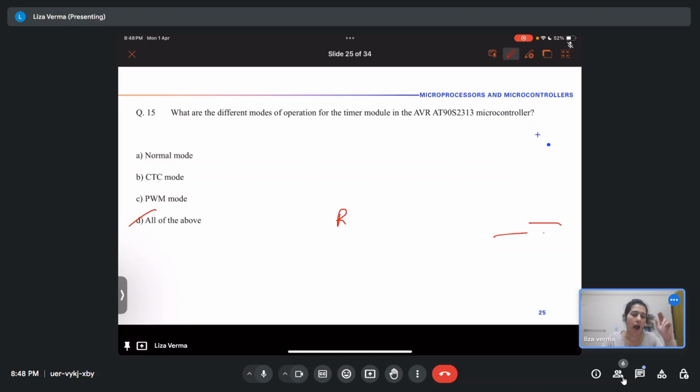For normal adding, ADD R0, R1, R2. For affecting the flags, you write ADDS R0, R1, R2. That's it.